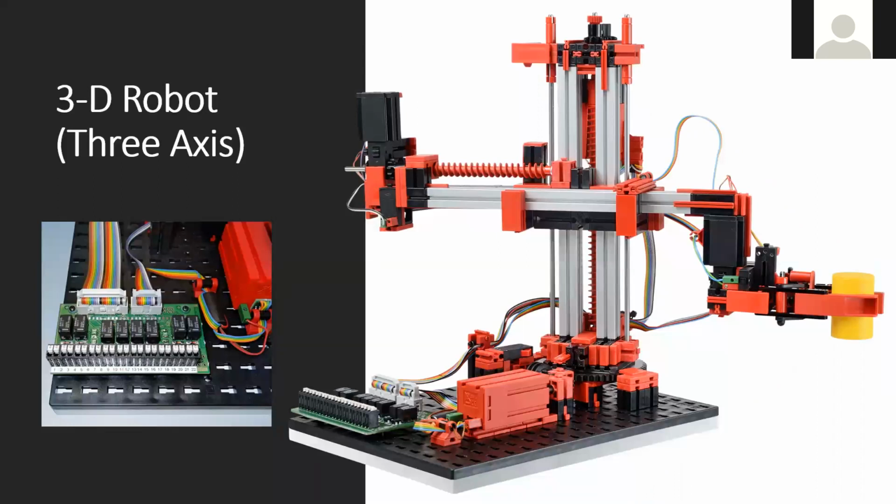Next is a variation on the idea of a pick-and-place robot, or the 3D or 3-axis robot. The 3-axis robot has gripping forceps, which it uses to help it quickly and precisely position the workpieces it picks up in 3-dimensional space. The degrees of freedom for the robot are as follows. Axis 1 turns 180 degrees, Axis 2 can move forward or backwards 90 millimeters, and Axis 3 can raise or lower 150 millimeters.